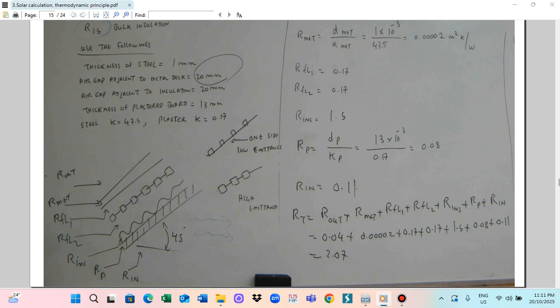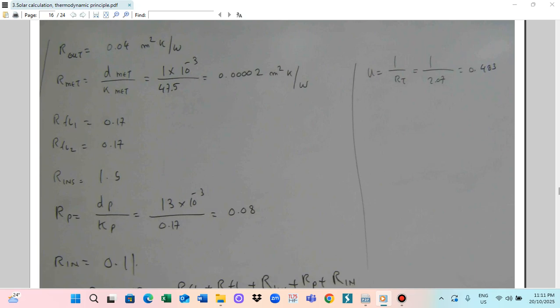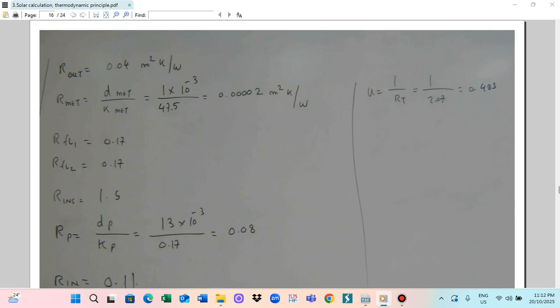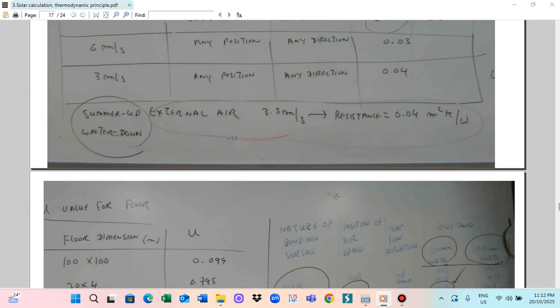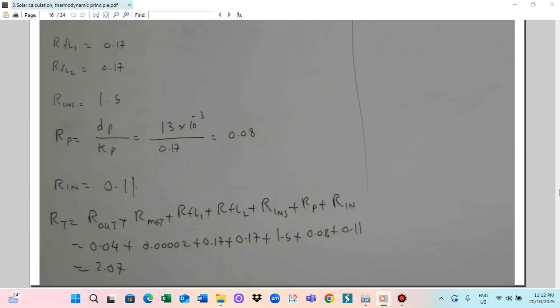But this one is this area, this area is common. So when you see from the top, this area is D, and this is H1. So this side multiplied by this side is the area. So this area is 2 into T1 H1. So this is the total area of the roof you can calculate, and then you can calculate total heat. Total heat flow is equal to U multiplied by A total. Then you get the total heat flow. So by this way you know how much heat flows into your house.